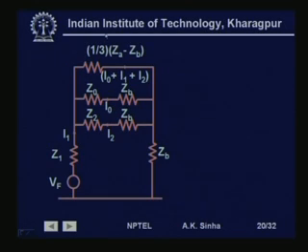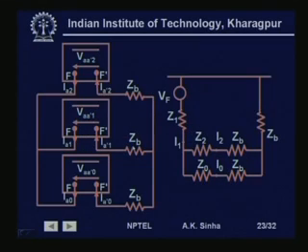So, with this, if we go back to this circuit, what we find is that substituting ZA equal to infinite means this becomes infinite. So, this is an open circuit, and the rest of the circuit we do not have ZA. So, the rest of the circuit remains as it is. So, this is what we get in this case, that is, this is the system that we have, where here we had ZA minus Z1 by 3 (ZA minus ZB), that part is now infinite.